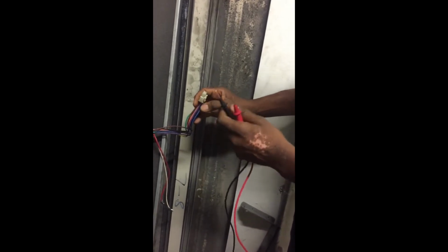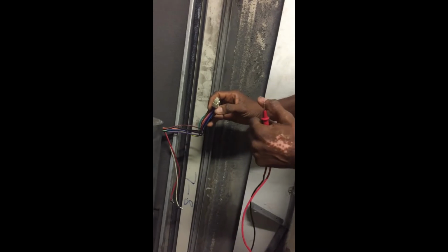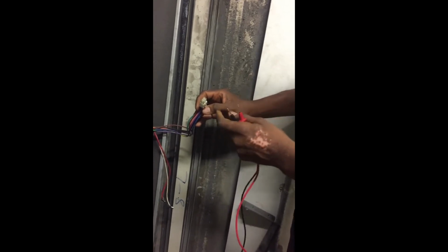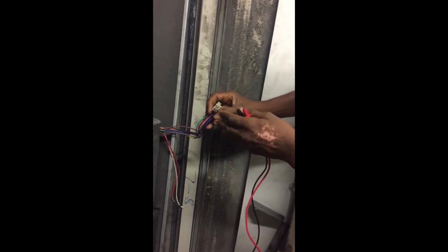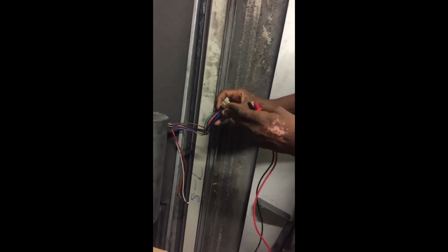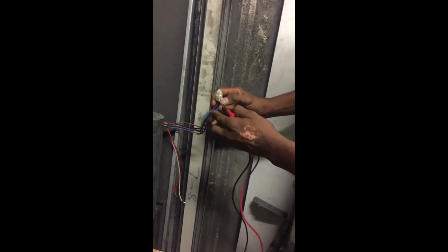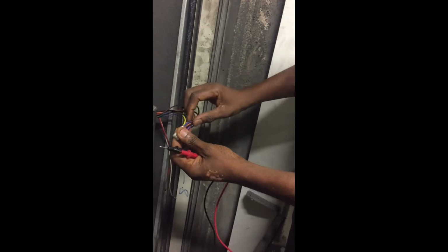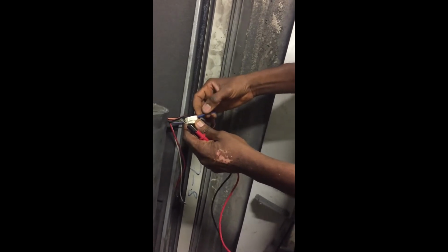From that cable that is the neutral, you are very sure that as you test with one leg on that neutral cable and the other leg on any of the speed cables, you're going to get varying resistance. The high speed should have the lowest resistance, while the low speed should have the highest resistance. So in this particular case, let's assume this is clearly earth, and I believe that this blue is most likely the neutral cable or the common cable.